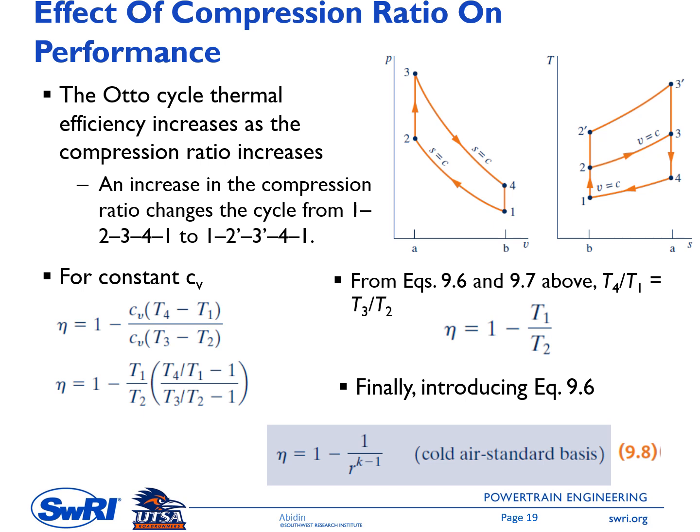And then we can analyze the performance of this new compression ratio. In this case, we use cold air analysis, so we assume that Cv is constant.